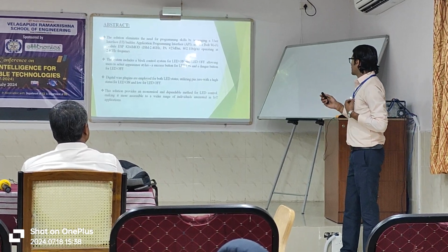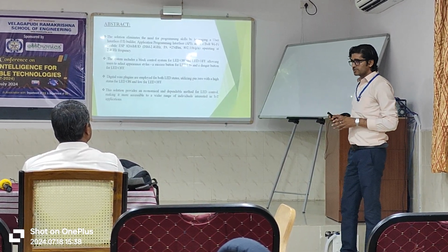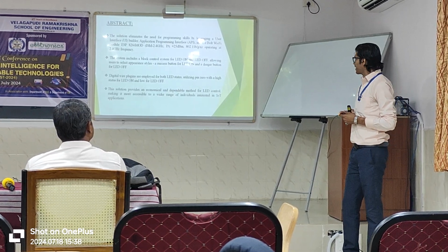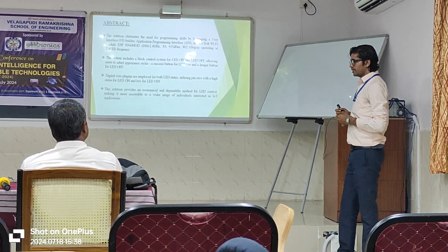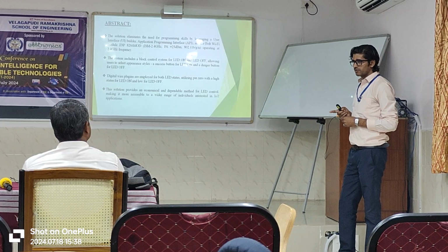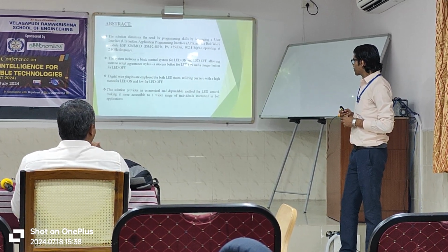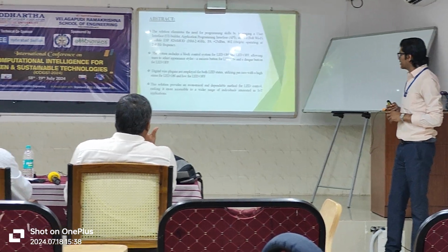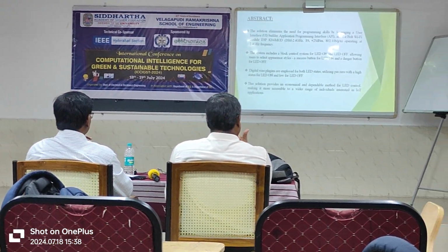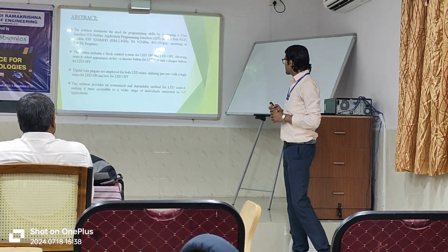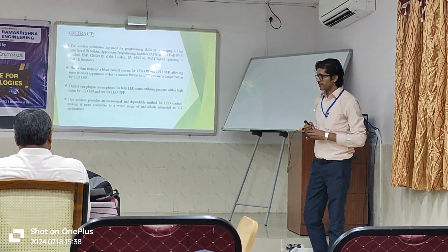So it uses the user interface and application programming interface, that is the API, to the ESP8266 module, which contains the ISM 2.4 GHz band and 25 dBm power amplifier and 802.11 BGN operating at 2.4 GHz frequencies.